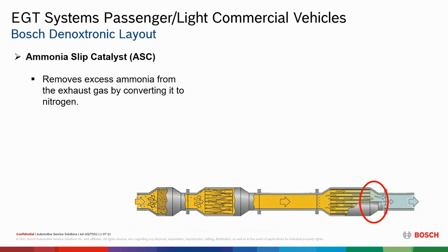So now, and these are all within the same can as well now. The beginning ones were a separate can. Now they're joined together with the SCR. And the SCR with that ammonia slip at the back of there, the very end of that converter, is now taking care of that ammonia slip, is what we call that, to eliminate the ammonia, burn it off so we don't have that excess ammonia going out the tailpipe. All working good. We have harmless gases coming out the tailpipe, I hope.